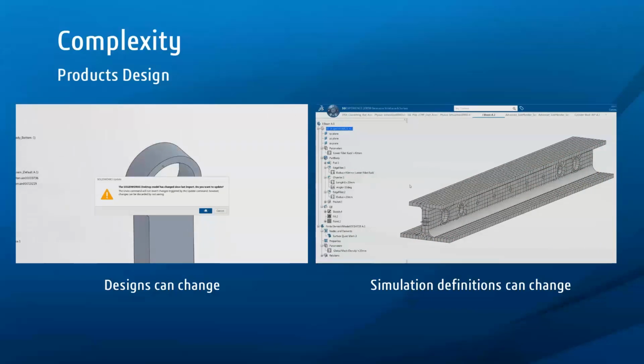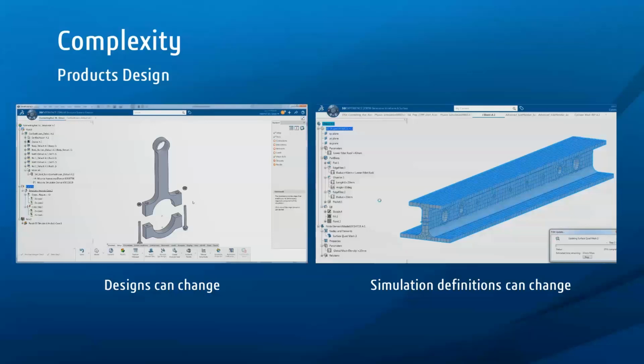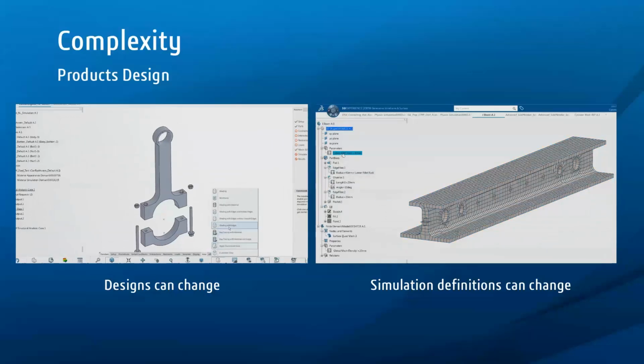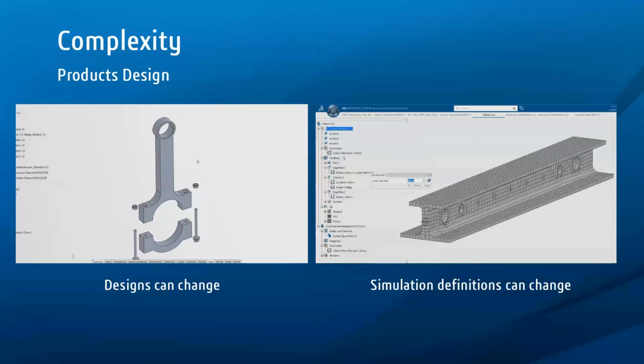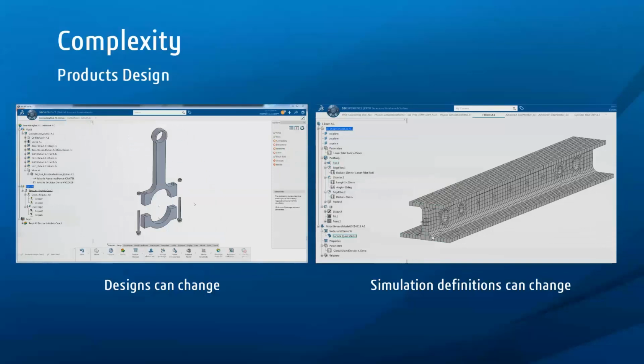The Managed Data Model on the 3DEXPERIENCE platform also allows for parameterized CAD and simulation features for quick modification during methods development. For example, these parameters can be linked to mesh densities on certain structures, so the user doesn't need to navigate a large product structure, the meshes, the finite element models, just to make a small change.